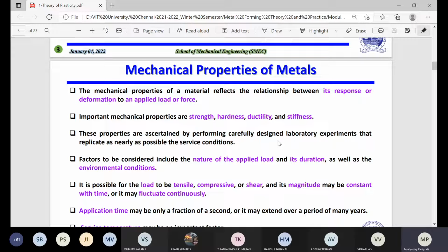The moment you go from laboratory scale, you have to go for the pilot scale. Pilot means a little bigger amount. Let's say you are making 2 gram, 5 gram, or maybe 6 gram, then you have to go for maybe 30 kg, or 40 kg or 50 kg. Then after success again, because you will find a difference here: here 5 gram, here you are taking 30 kg. So you will find a lot of difference there. Then when you succeed, again you have to go for the industrial scale or the large scale.